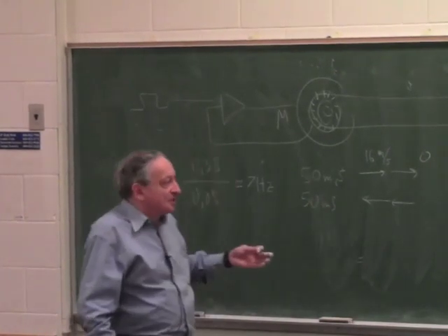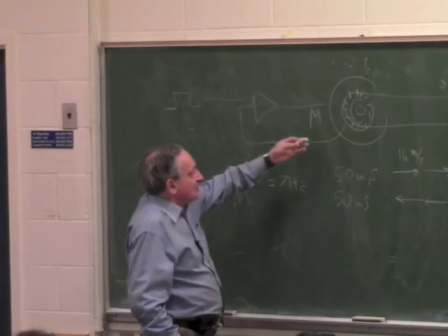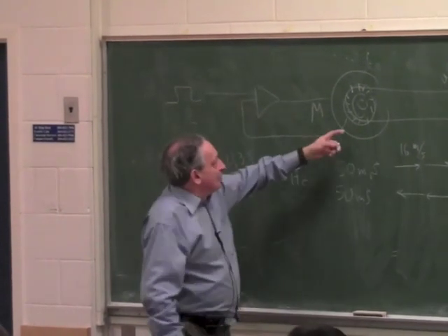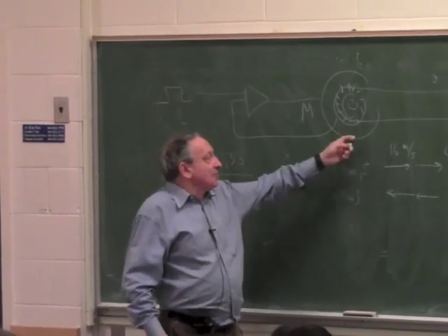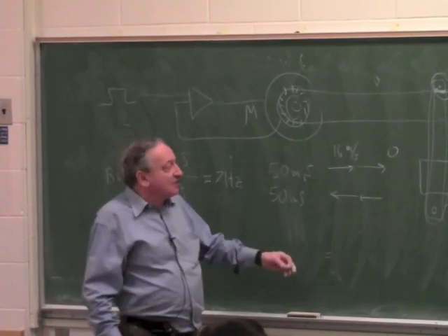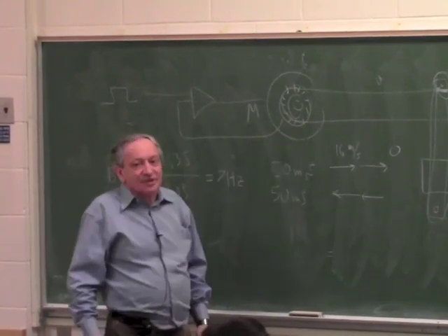So obviously it's not a stepper motor, which means we have to have some other motor, say an induction motor. Okay, and then it means we have to have an encoder. Could be a DC motor as well, but still means you have to have an encoder. So in terms of sensor, a regular encoder is good enough.